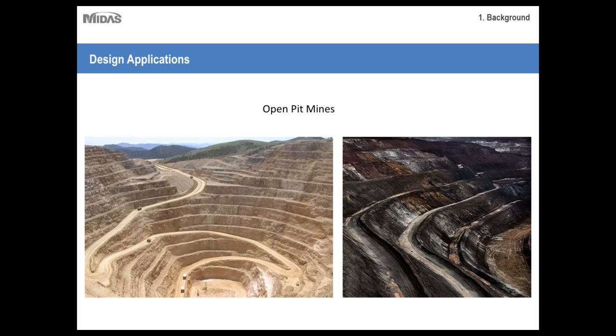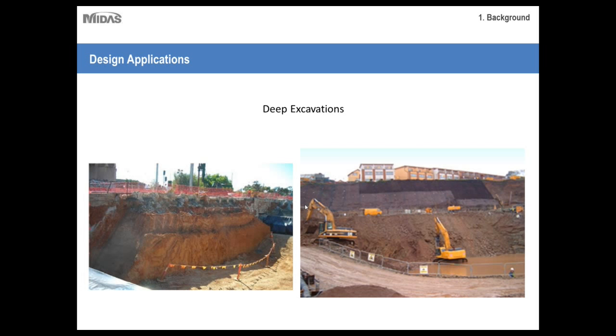Also, dewatering bores may be used to relieve water pressure by drilling horizontally into these walls, which is often enough to cause failures in the wall by itself. So even though rock slopes are naturally much more stable than soil slopes, there's still various things to consider, and there still are instances when structural reinforcements might be needed, especially for open pit mines, which consist of several layers of slopes.